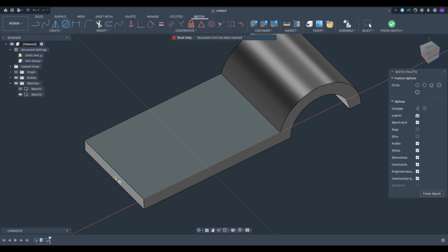Same thing. You move your mouse till it makes a triangle there, triangle there, and then Fusion will remember them, and you'll see it gives me two guidelines, and it kind of locks or snaps your mouse into it. So that means it's the center of basically this rectangle. See, I lost position again because that'll happen. You just move around too much and stuff happens. Same thing. Get the center there, lock it in, and we're in the center.